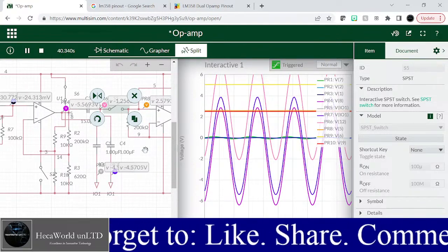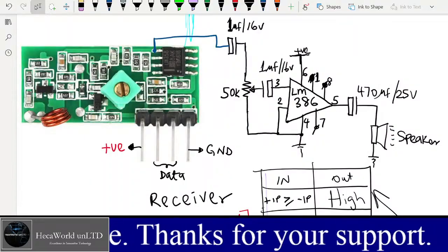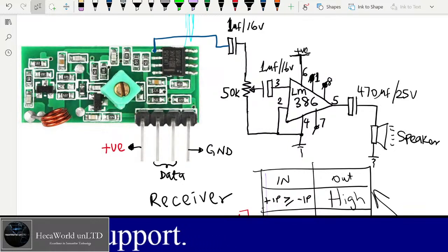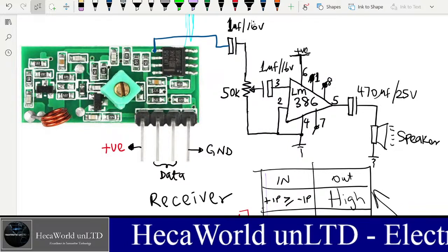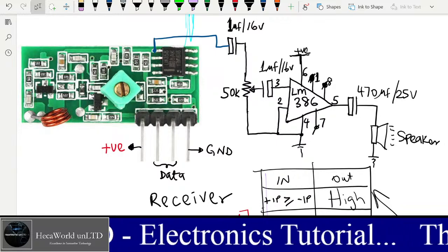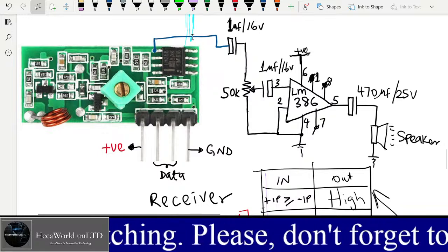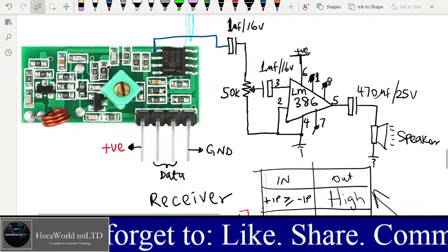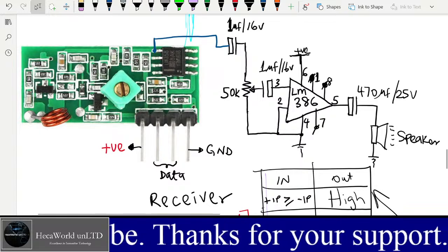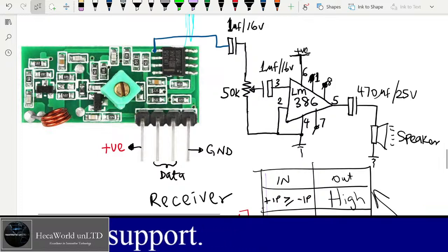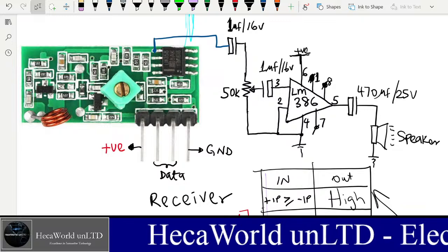What we're going to do in our next video is, and you can do this before us, there's no secret here. What you can do is go ahead and pull that pin 4, which should be this pin here. The good thing here is that the pin is on the outside, so you can desolder that and pull it up, and then connect a signal from there. Connect a wire from there to the center. So we're going to do something like this.